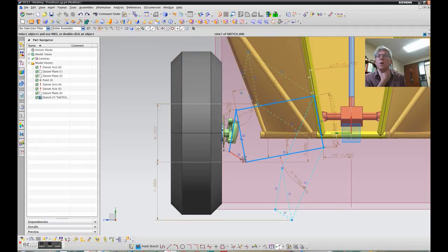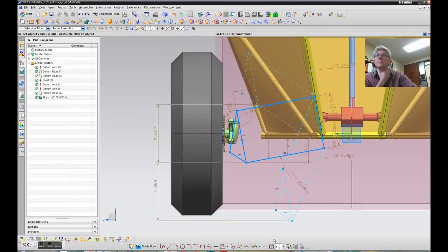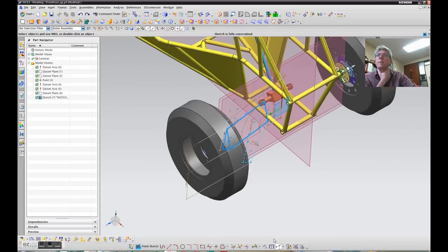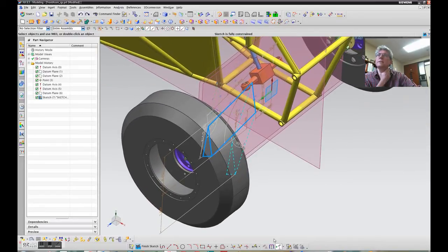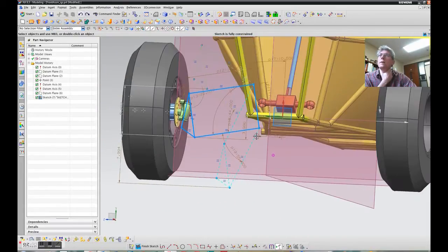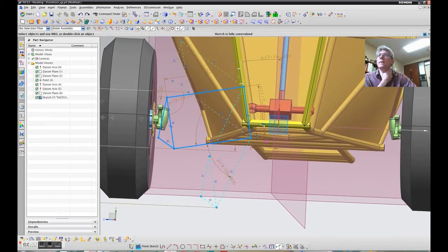So now I would highly recommend doing something like this, getting agreement upon where this should all be. Now I know that at least my design requirement of the travel makes sense, right? And then I can go look at it in context of how it mounts to the frame. So I will probably need to make a little mounting lug down here, and likewise here and here, and have those go to the frame.